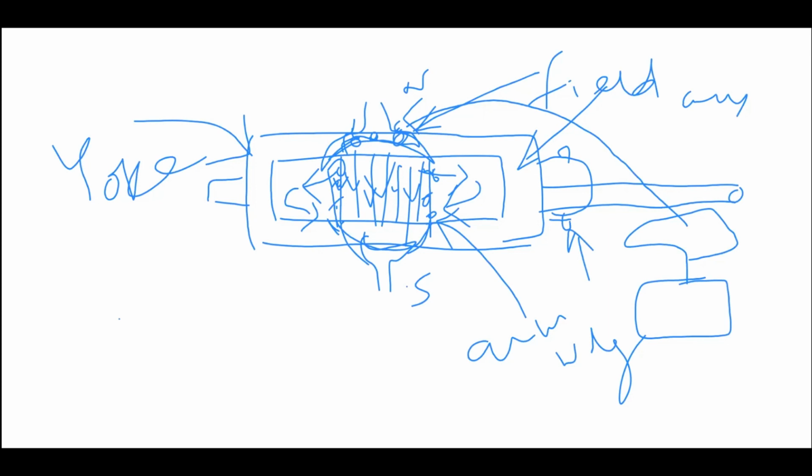What is the general diagram of the DC machine? We just draw the armature, and these two toppings are there. These toppings are nothing but the brushes. These brushes can be of copper or carbon. Copper brushes are more superior because the drop is less in the case of copper brushes.